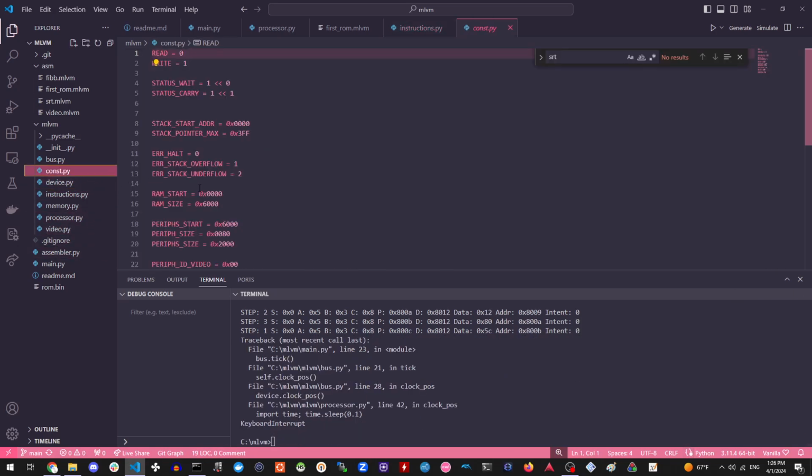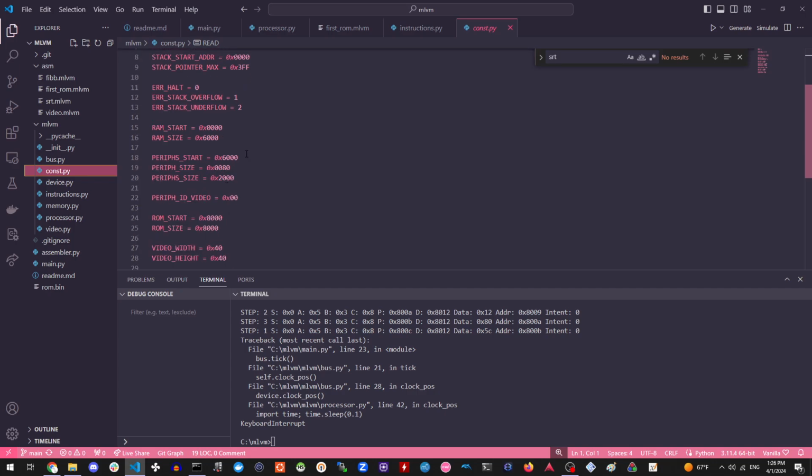I decided I wanted to add a peripheral system where I can hook up any number of components that all just have a few registers that can be written to, and then they handle their own memory, or they handle whatever they need to do on their own, with a unified SPI protocol to them, basically. So we have a 2K block in the address range just for peripherals, and then each peripheral gets 0x80 bytes of registers that it can possibly listen on.